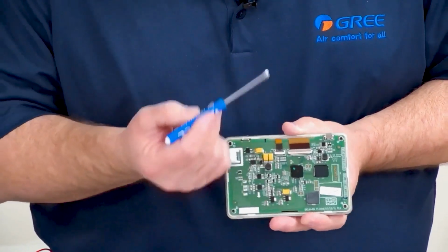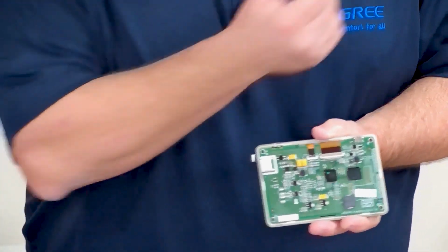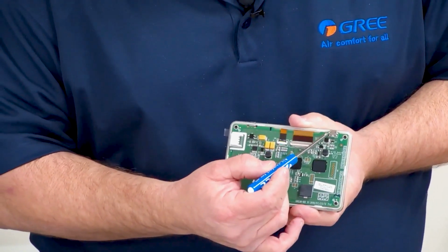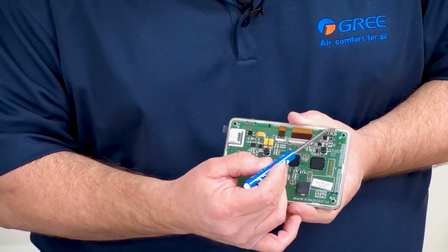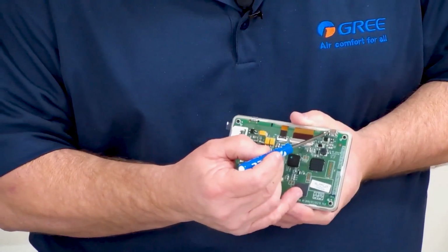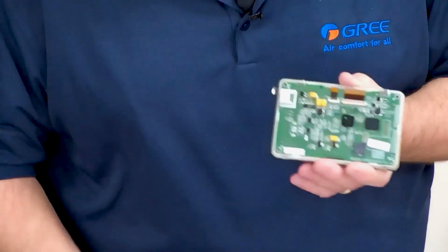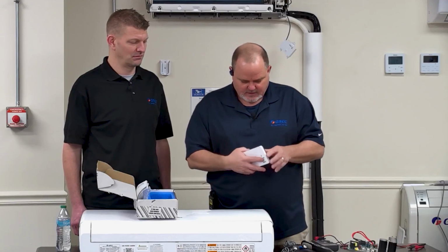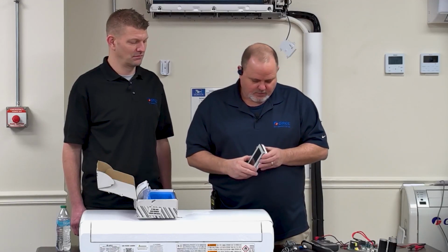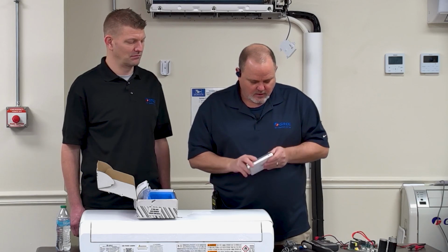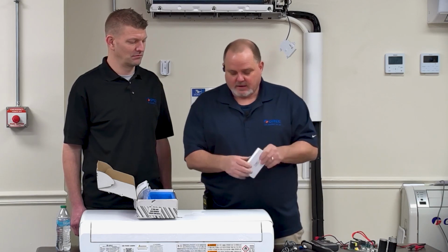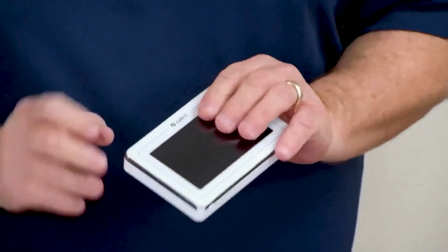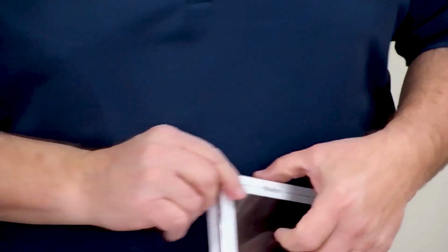So this one hasn't been done yet, but my tool over there, I pop it apart and just get a hot glue gun and put a little bead of hot glue across the back here. Don't block your port, but just a little bit of hot glue over it, let that dry, and then you can pop the tool back together. Like I said, it literally comes apart super easy and pops right back together. Now that port is glued, it's solid. Plug it and unplug it, and you're not going to break the service tool. We've tried and tested that.